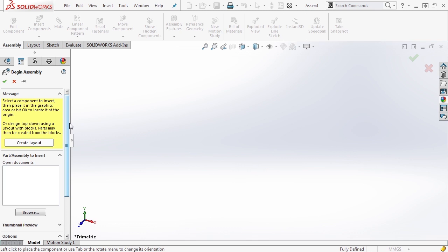Once we start to create an assembly, I'll start talking about references and where they're looking and so on. But it's very important that you understand that from the get-go, because you can't just bring parts into an assembly and assume that they're always there. Because if you don't send them in, especially if it's like a toolbox component or some other downloaded component that's in a different directory, they might move, they might get lost, and it might really mess up your assembly.